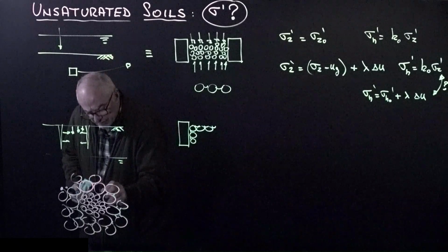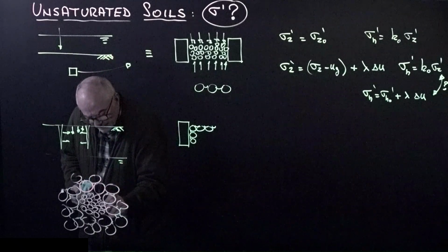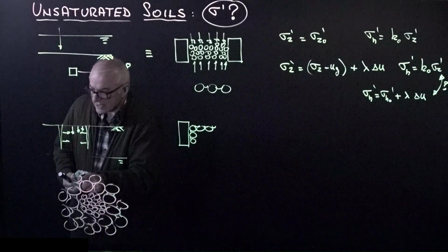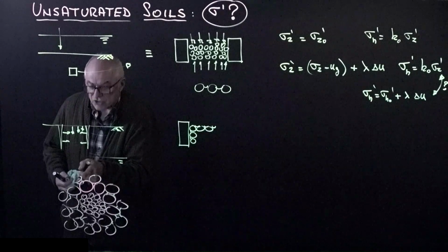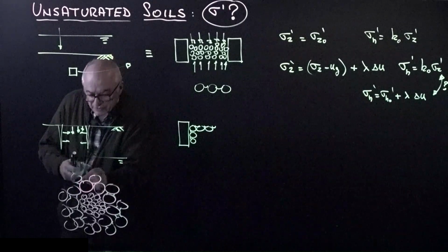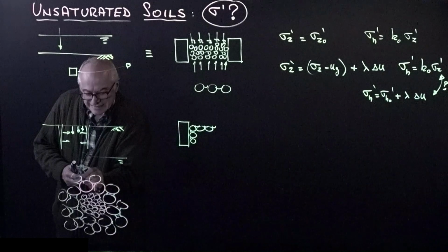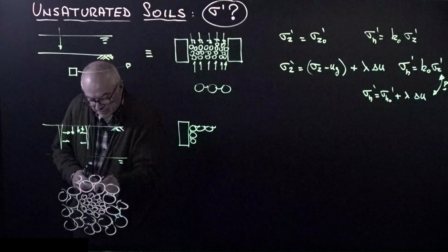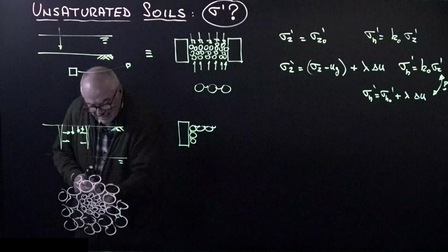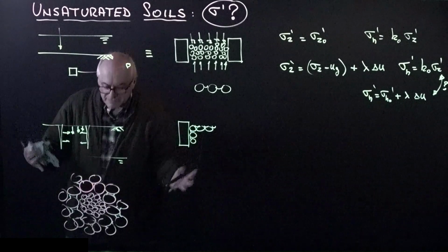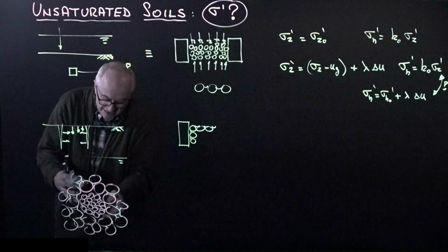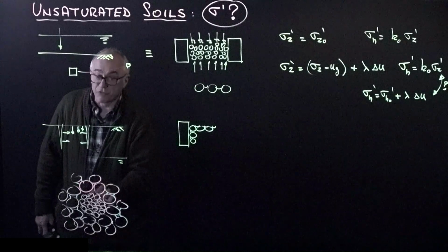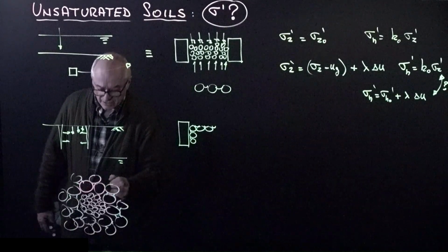And so we put the menisci at the boundaries here, and as you can imagine, this water between the large grains is under suction and is pulling the grains together to the extent of that small radius of the water at menisci, called the pendular regime. However, this lens is all surrounded like a latex membrane, which is the interfacial tension that is bringing all together. So all this is feeling the full effect of suction.